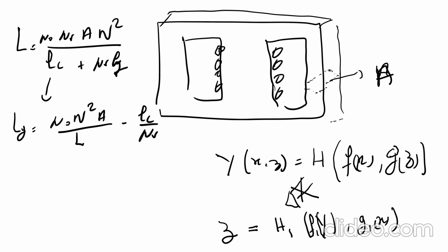So to correct the expression of the air gap, here the cross section is hidden in the equation, in the value of your inductance. This equation is only correct if you relate the cross section to the value of your inductance. You have to write it in a way that the inductance is calculated for that given cross section, and you cannot sweep the cross section.